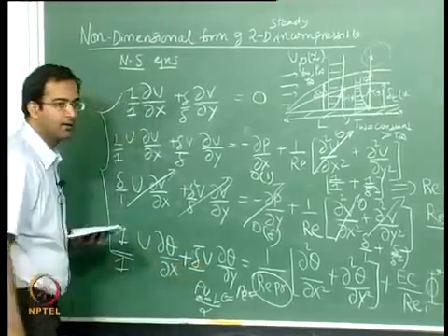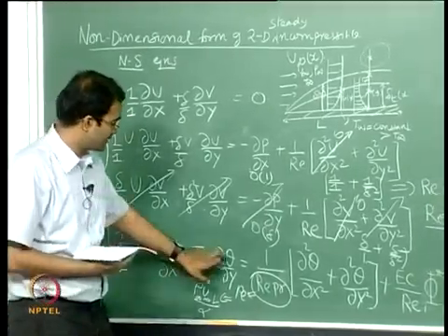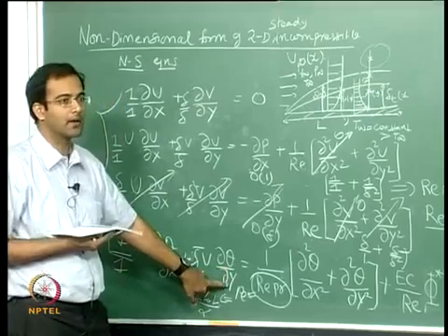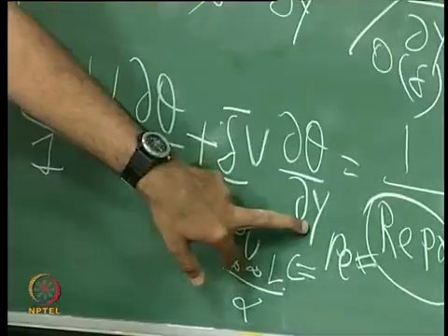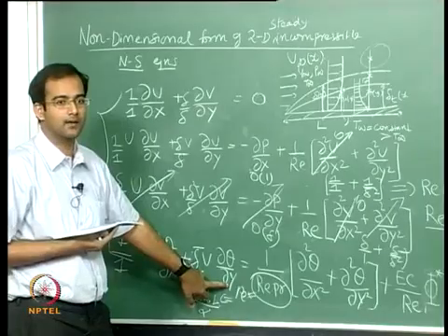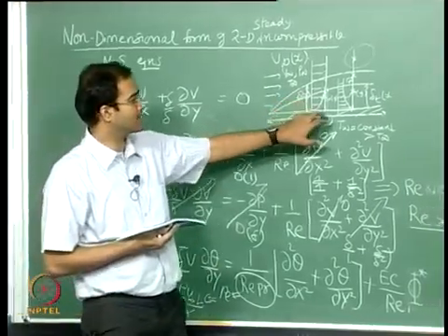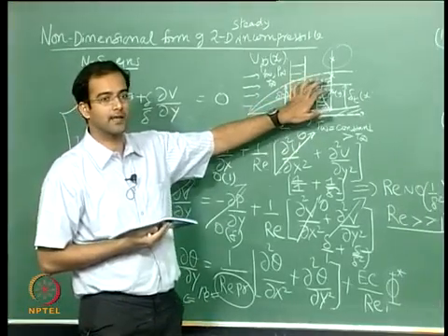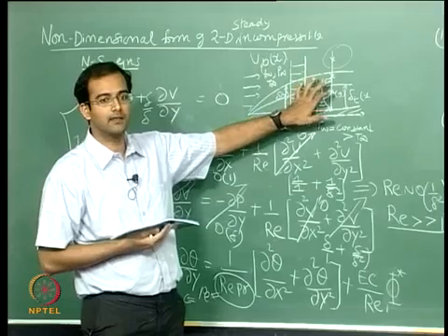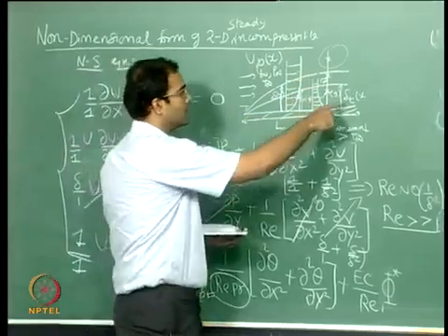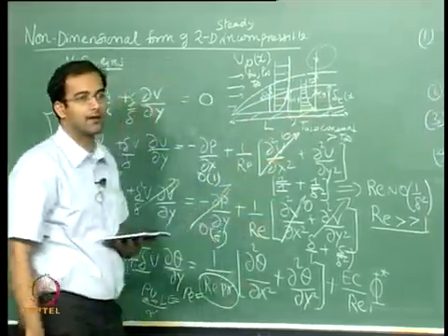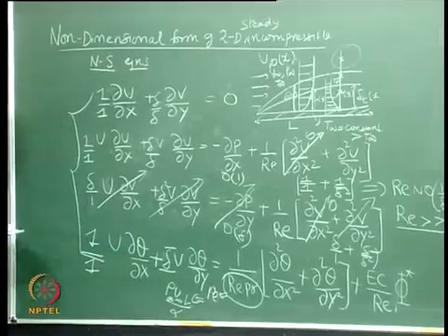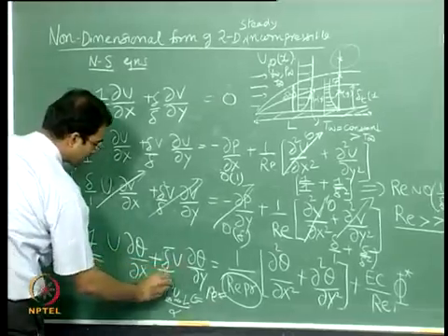Now when we are considering the temperature gradient, which boundary layer do we have to look at? Thermal boundary layer. So for temperature gradients in the thermal boundary layer, our y scales with delta T, so therefore we have to use this as the scaling parameter. So we will say that this goes as delta T bar.